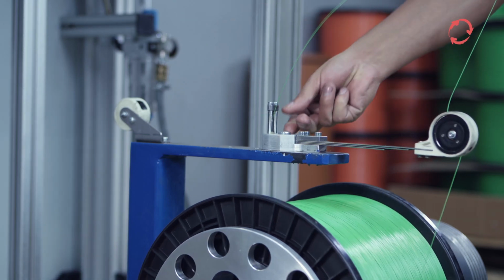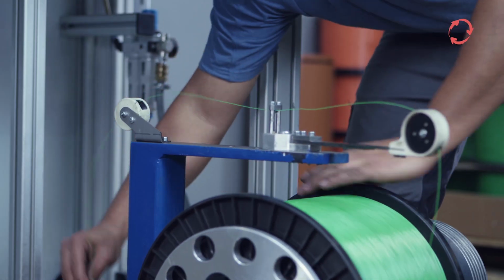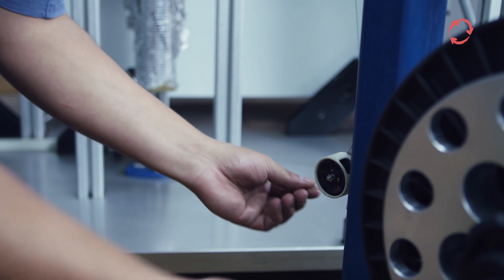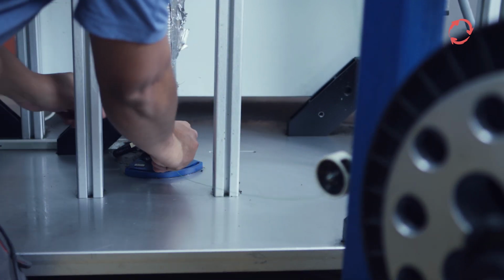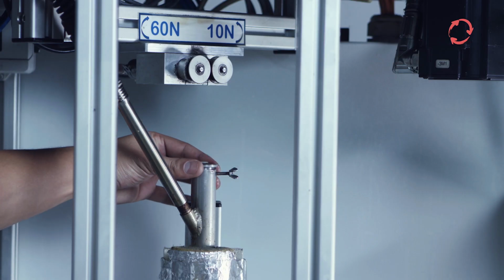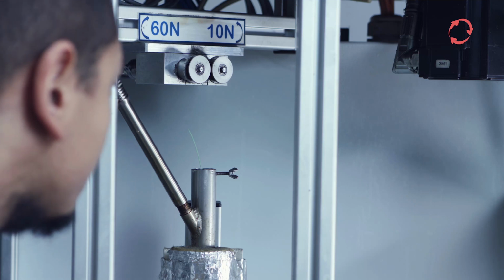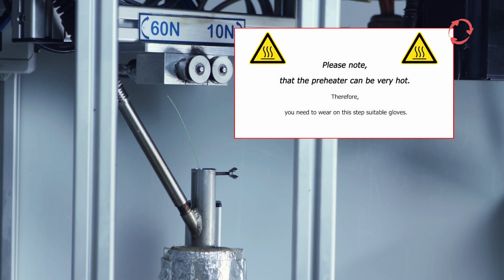Guide the thread through the two deflecting pins towards the second deflection roller. From there on, guide it further down to the third deflection roller. The thread is guided through the third deflection roller. This location is the transition from the tangential unwinder to the machine, diagonally to the fourth deflection roller. The thread is pulled through the fourth deflection roller to the preheater. In order to facilitate the thread's exit, the lid of the preheater can be loosened with a thumb screw and removed.